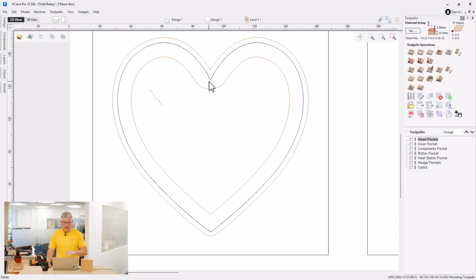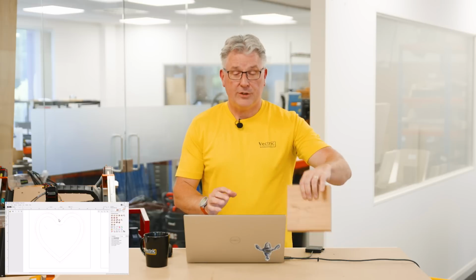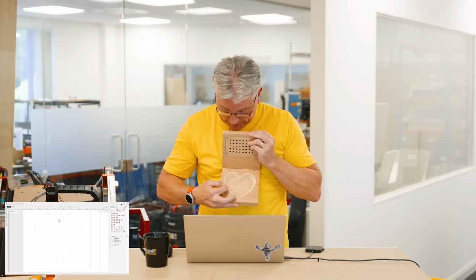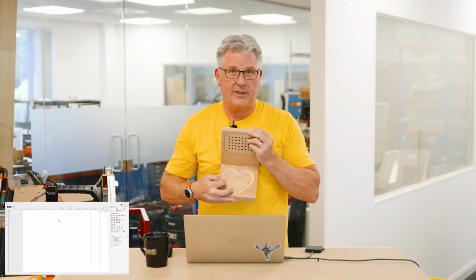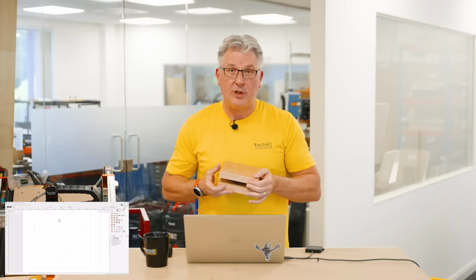And then what I've done is I've offset that line inwards, the width of this cross section. That's important because I'm going to use part of this line to create my cutout pass. Now remember I talked about you might want to put a little shelf at the top of this, and you can use the boundary or your automatic boundary for that if you want to, but I couldn't. So for me to achieve that, what I need to do is actually create an offset the other way, the thickness of that top edge, which for me is this size right here, about 1/8 of an inch or so, 1/4 of an inch I think it is. And I'll convert that to millimeters, but that's what it is right there. And so that's what I'm going to use that for.